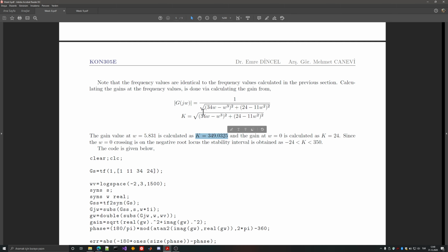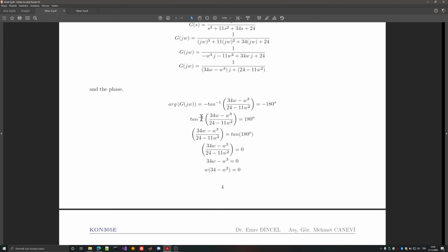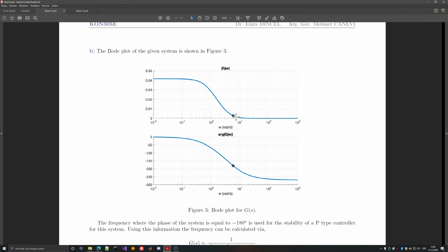So you have to check again what the Bode plot looks like, or what your calculations will give you, because if you're looking for the point where minus 180 degrees is satisfied, you will get the positive one. If we have 0, because k will be negative and this negative one has minus 180 degrees, then you're dealing with the negative bound.